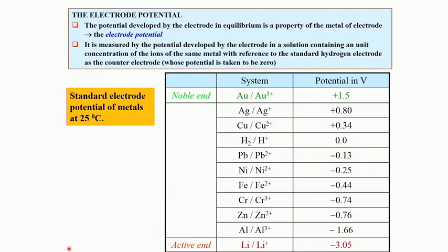Now, if you quickly go through the tendency of different metallic materials to corrode, you will find that they vary a lot. It depends on the typical free energy change associated with the process of corrosion. As I mentioned, the metallic state is the unstable state, so whenever it corrodes naturally, there is a decrease in free energy. This particular free energy change is usually negative. So, the negative Gibbs free energy change is basically the driving force for corrosion.